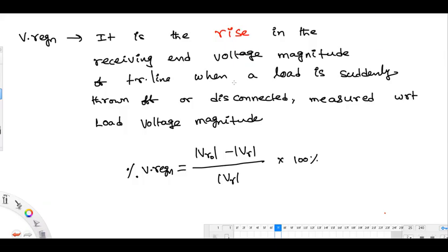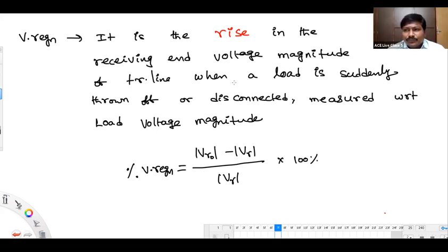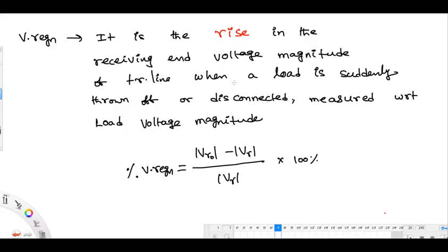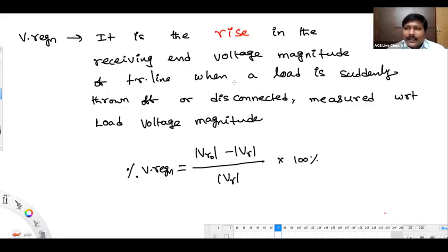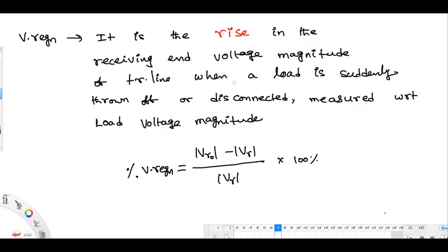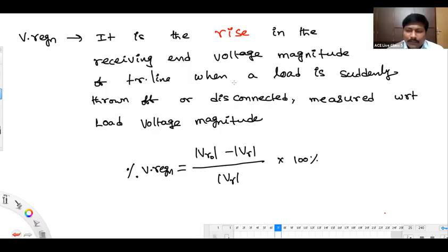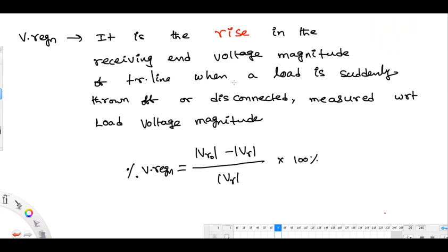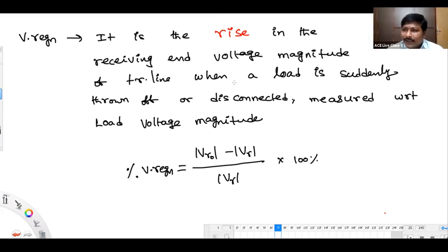But when we go for a long transmission line, then that will be distributed. That's the approximation they will do. If you use the distributed model there, the analysis will become even more laborious. Approximate means we have an equivalent pi or equivalent T, a lump. But here it is written that the distributed model has to be used in a transient analysis. That is the assumption we are making.